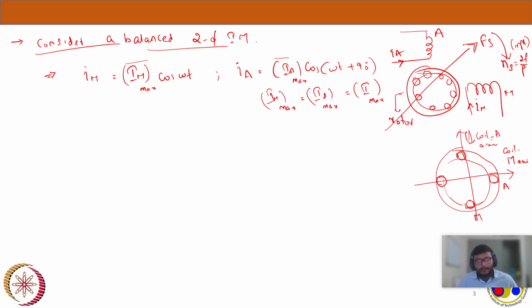That is okay. But the reason people don't usually use these two-phase machines is that three-phase supplies are very popular. That's why three-phase induction machines are very popular. If we have a two-phase balanced induction machine and want to rotate it, we have to convert the three-phase supply into a two-phase supply.